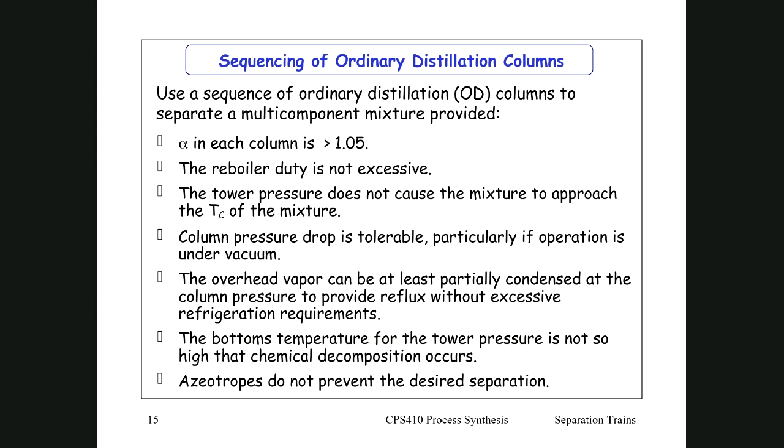Okay, so that leads on to the second point. The reboiler duty must not be excessive, and that is simply either you must use lots of plates, or you must have a high reflux ratio. And if there's a high reflux ratio, the reboiler duty will immediately increase.